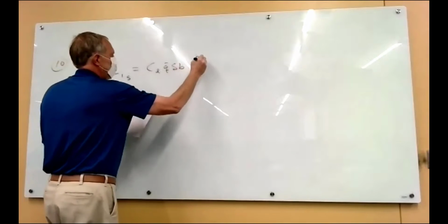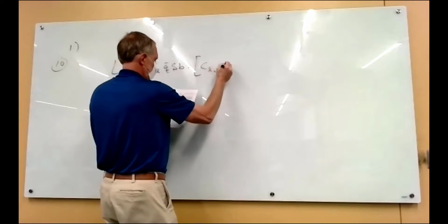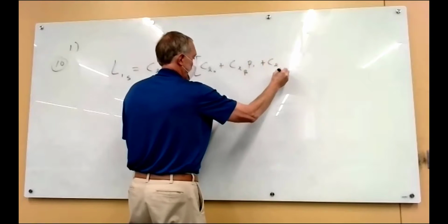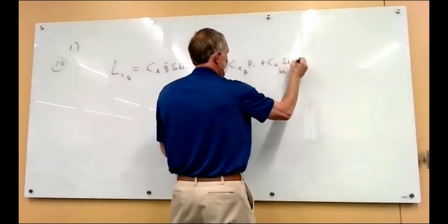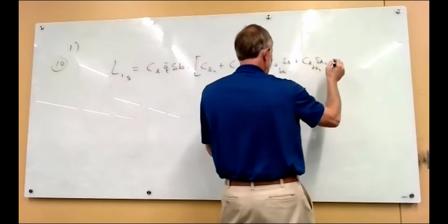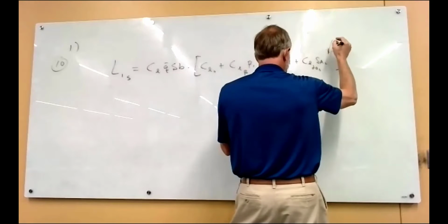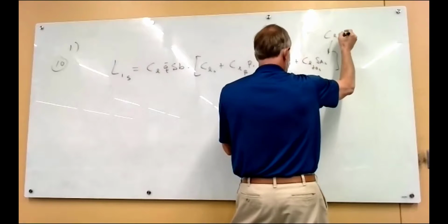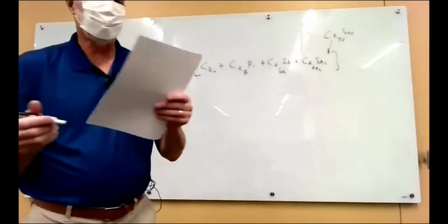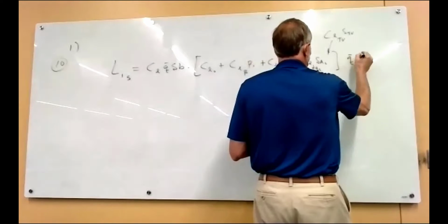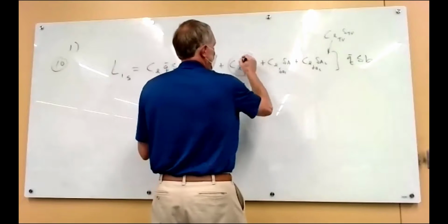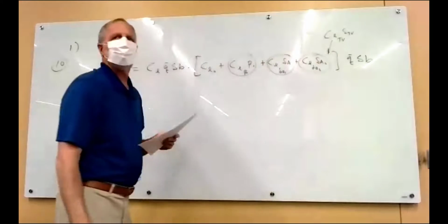So the linear model for this, the rolling moment. The difference between this and our normal model is there's 2 ailerons, so you have to put both of those in. Optionally, you could have put the thrust vectoring in here. I didn't require that because you could assume the thrust vectoring did not roll the airplane. So the points were given for this term, and this term included those.